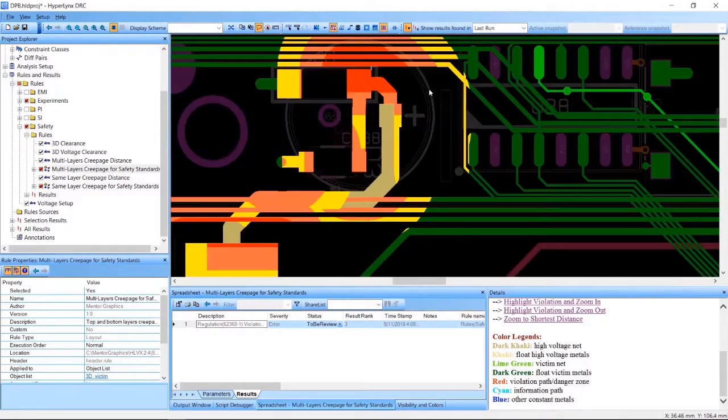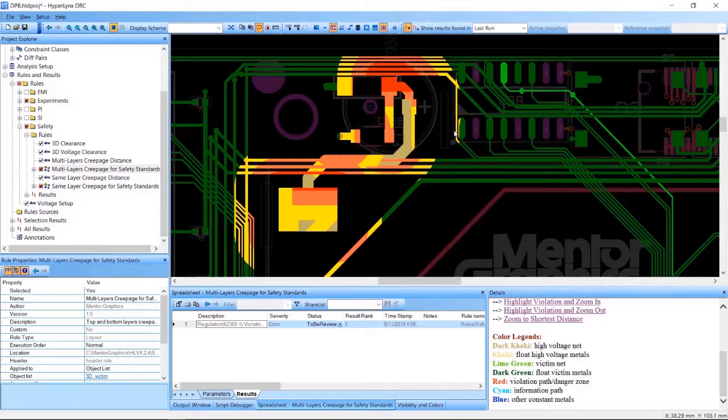We actually have an extension of the victim net here in dark green, showing other considerations of what would be the victim net because of their floating metal, because they're that object C in our example earlier. The clearance distance here would not just be between object 1, the main 200 volt net, and the lime green victim net. There's no just minimum creepage distance here around the cutout. The victim net is floating to these nearby metals and nearby signal traces.